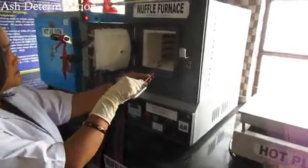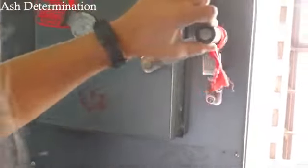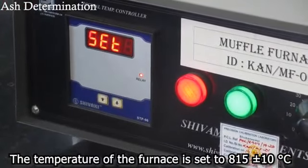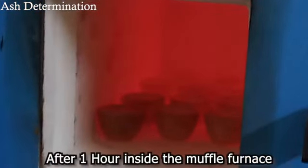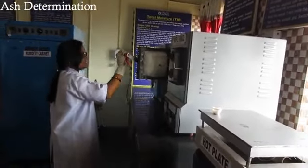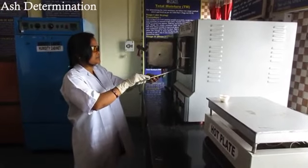The uncovered disc is inserted into the muffle furnace at room temperature. The coal sample is heated in presence of air to 500 degrees Celsius for 30 minutes. Then the temperature is raised to 850 plus or minus 10 degrees Celsius in 30 to 60 minutes and maintained for 60 minutes. After that, the crucible is brought out from the muffle furnace and allowed to cool fast on a cold metal slab for 10 minutes and finally in a desiccator.